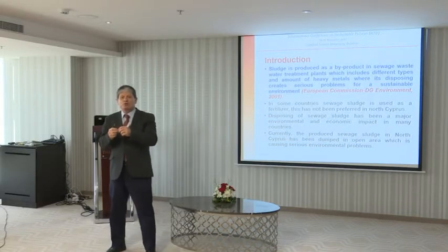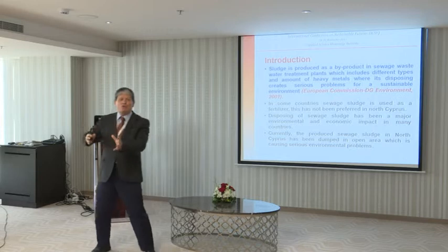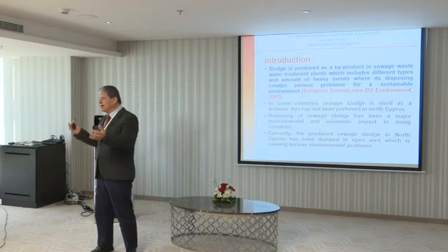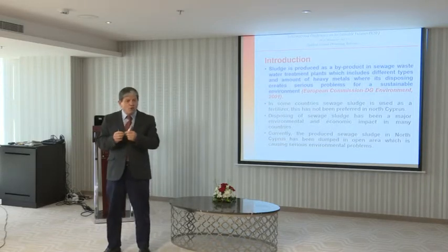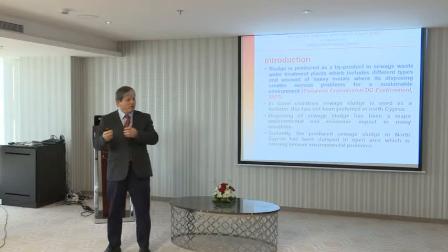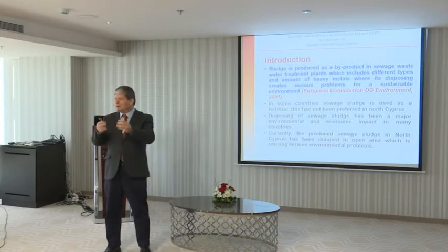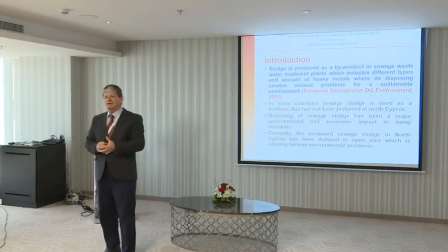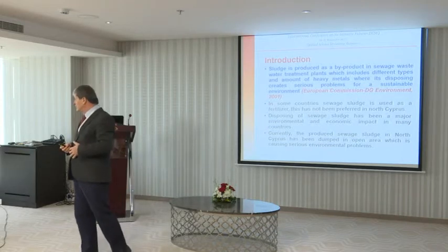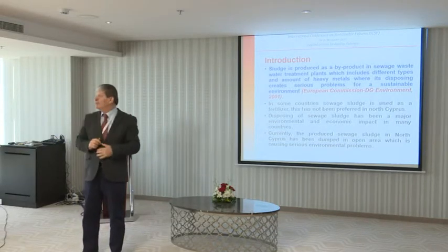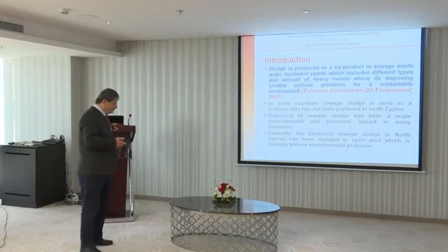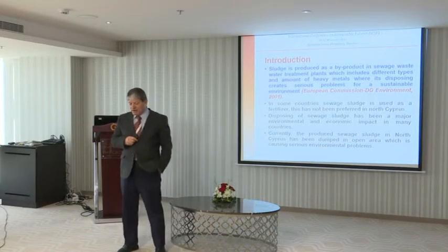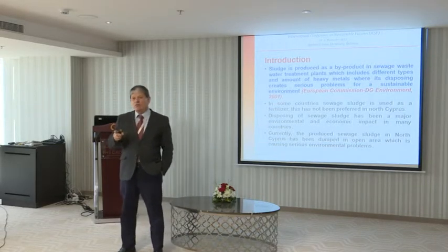The aim is not just to produce lightweight aggregate, but how we are going to use it. In Cyprus, as a hot country, we use foam concrete. First, using a chemical liquid, we produce a foam, mix it with mortar, and use it in concrete for heat insulation or sound insulation purposes, quite widely, especially for buildings. Our purpose is to use this lightweight aggregate in foam concrete.